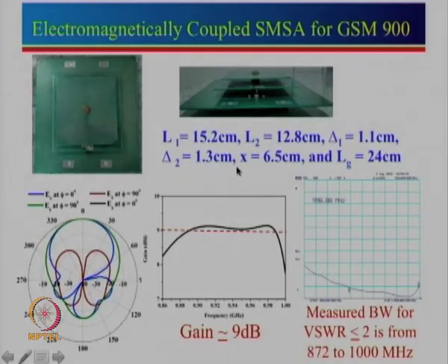So, corresponding to the lower band, this length was decided, and we chose the gap here so that we can realize the larger bandwidth to meet the requirement. So that is how we do the design here, and since air has epsilon r equal to 1, the effective dielectric constant is equal to 1 for this case.